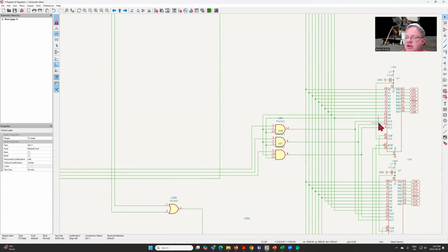So our 11th, 12th, and 13th address bit. And basically we pull in the contents of bit 9 and bit 10 and combine them with the contents of our EBANK. And so basically if both S9 and S10 are 1s, we will then pass through the contents of the EBANK register.